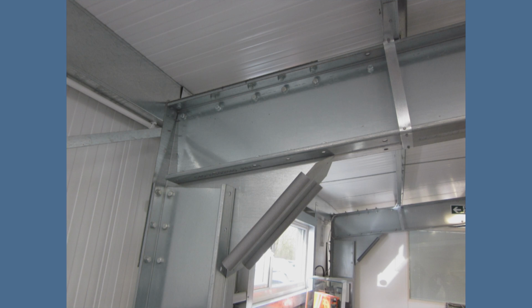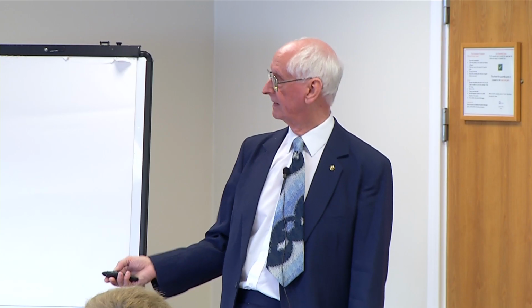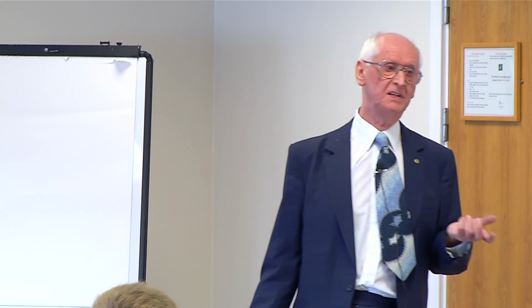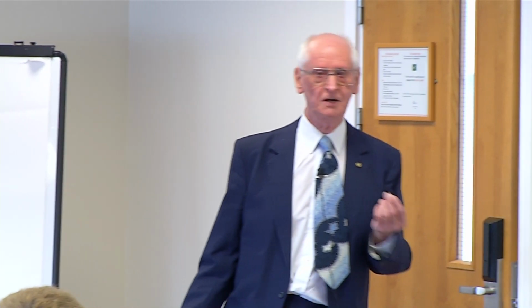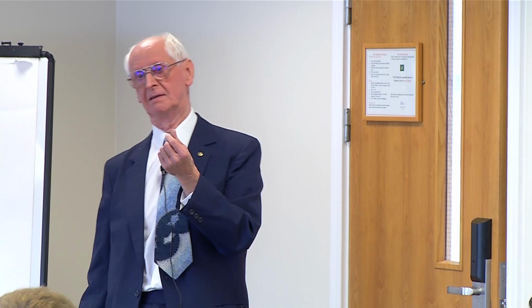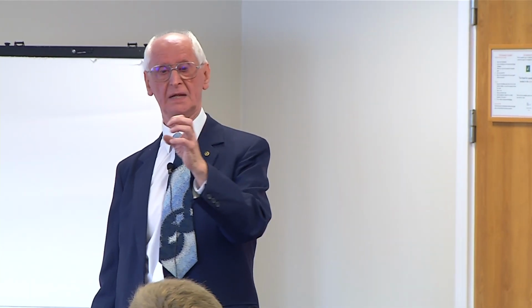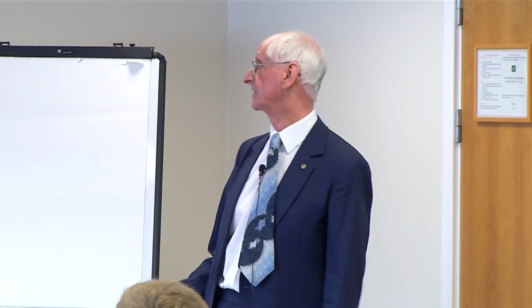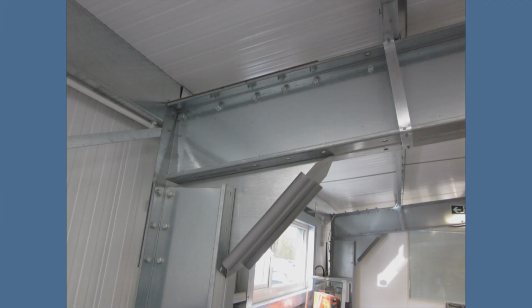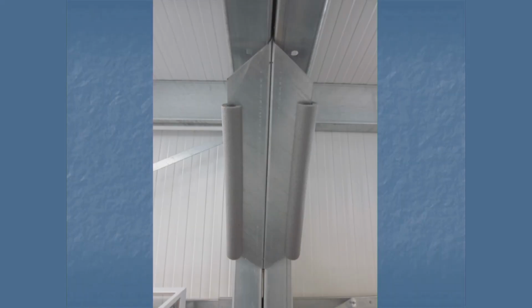And you can see here that this is just a piece of thin steel sheet bent into that shape with the bolts going through. Now, I mentioned before about washers under the nuts, but where you get a very, very thin section, we really should be putting washers under the head as well to spread that load into that thin metal so it doesn't actually pull through. And you can see how thin it is. You've got 2 of these sections together, back to back, forming the portal frame.